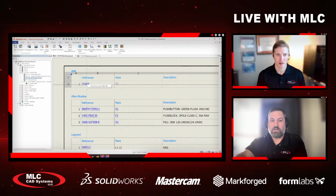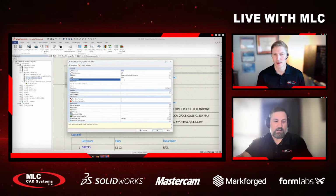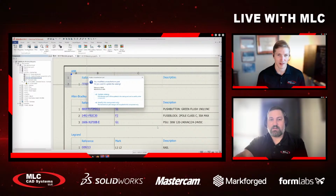Well, what we can do is we can go to the manufacturer part for this. And if I pull that up, you'll see it says ABB. There's that part number. You'll see that there's an article number field. This article number is built into the software. And I can say that this is ABC123. You're seeing me make this change right here. I can then hit OK. It will ask me, do I want to update my catalog? Essentially, do you want to update your library so all of them use this moving forward, or do you want to only modify this one? I put some generic data in here, so we're going to say modify this component only.